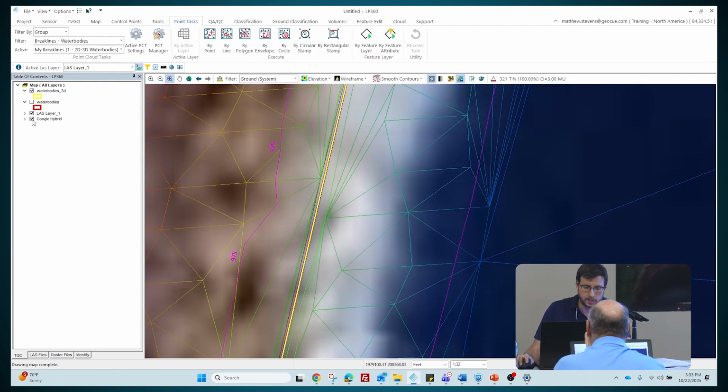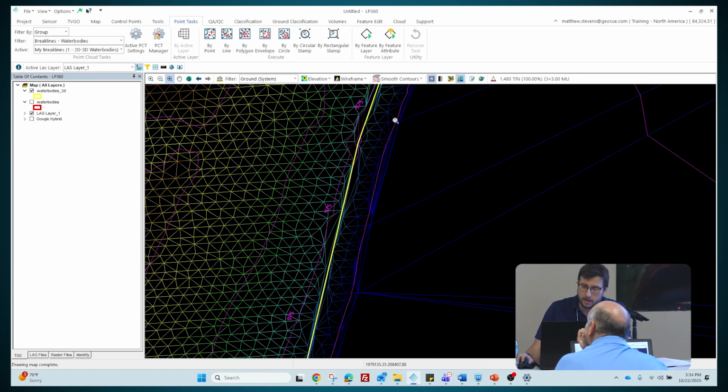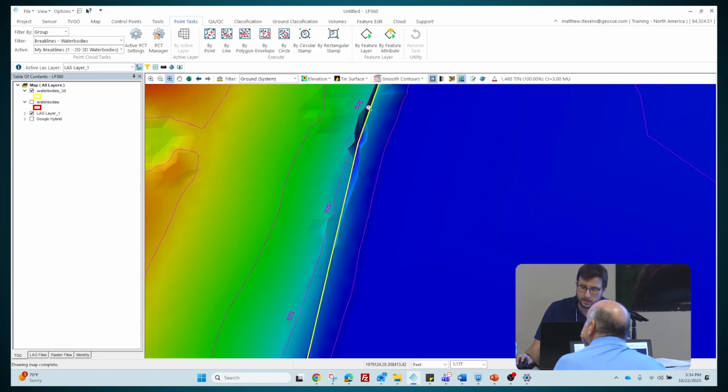I'm going to zoom in a little bit, just so I can see this a little bit better. You guys can do the same. I'm going to turn off my WMS layer so it's a little bit more visible in the black background. And after you've set the breakline setting, you can toggle it on and off, and you can see how we're changing that wireframe model. I'm going to switch this to 10 as well, here at the top. Switch that back to 10 surface, and we can just see how it's changing the surface in that spot. We still haven't done some things we need to do.